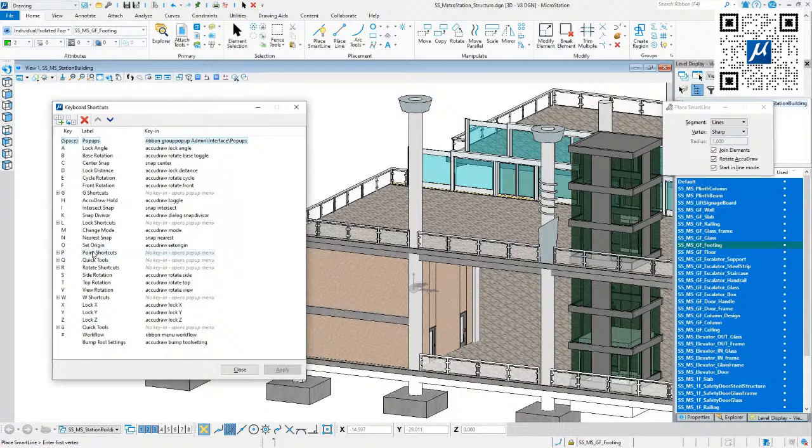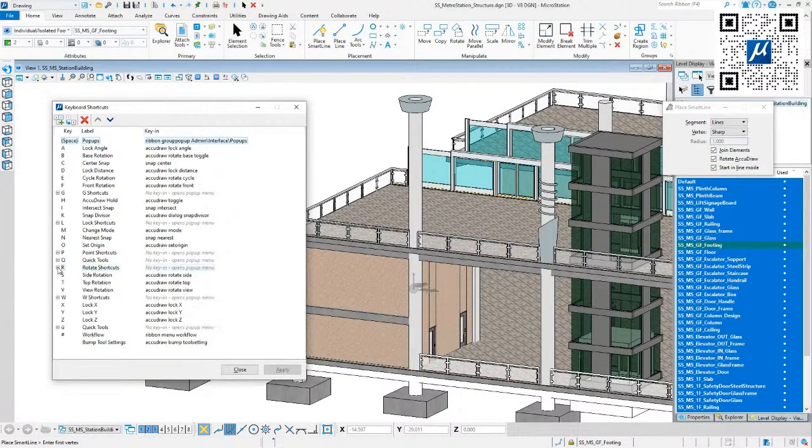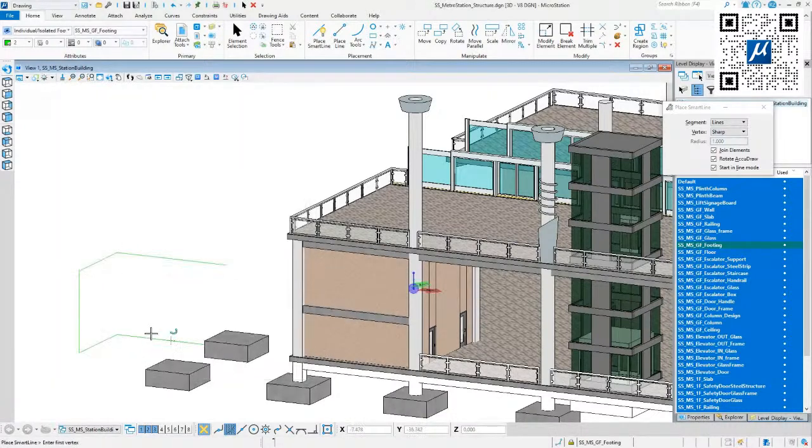You can see we got some rotation shortcuts like this, A, RC, or RE, many different options, and now I remember what I want to use. I want to use the RA shortcut, rotate ACS. Rotate ACS is just define a new coordinate system.